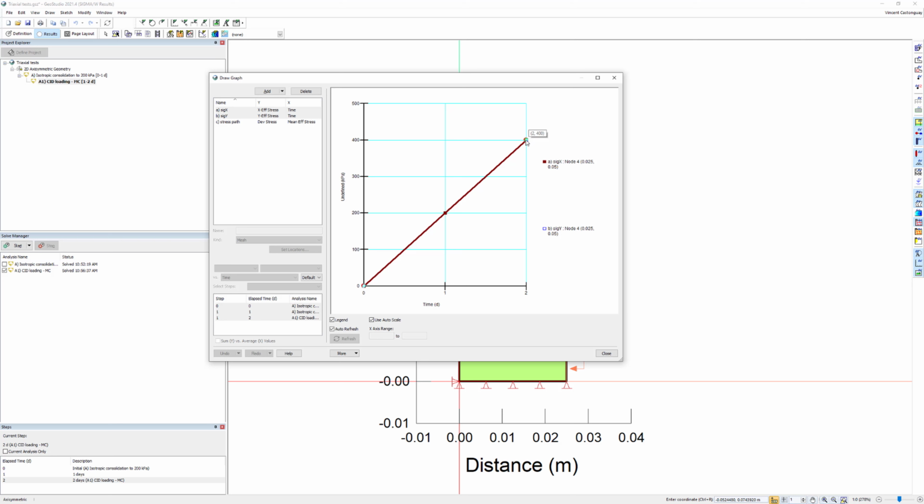Then on the second virtual day, the stresses increased again by 200 kPa, reaching 400 kPa. Clearly, the stress boundary conditions were applied once again on top of the existing stresses passed down by the consolidation parent. This demonstrates how careful one must be when deciding which boundary conditions should be applied from one loading step to the other.